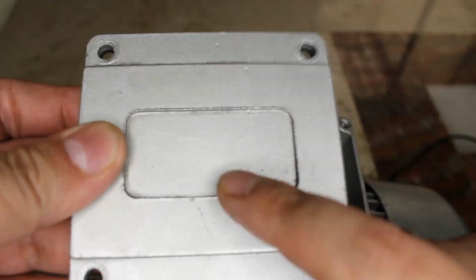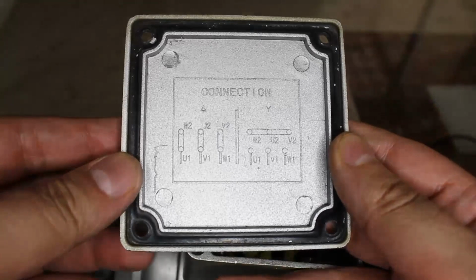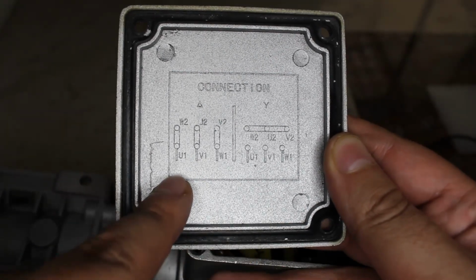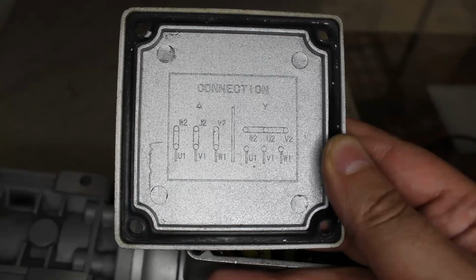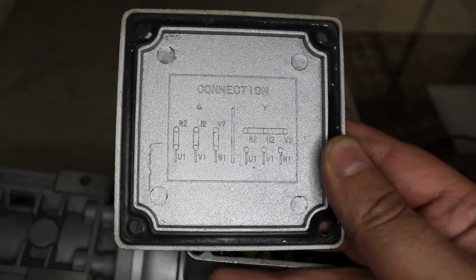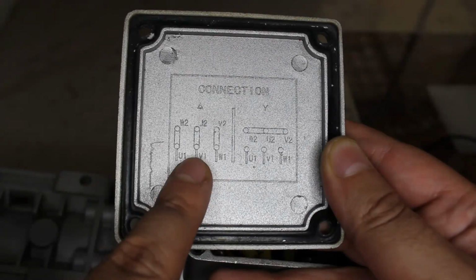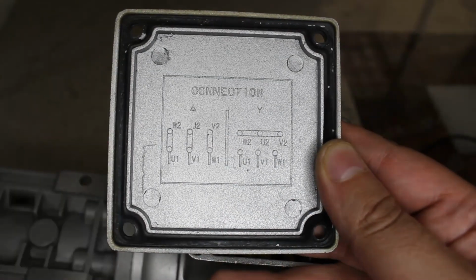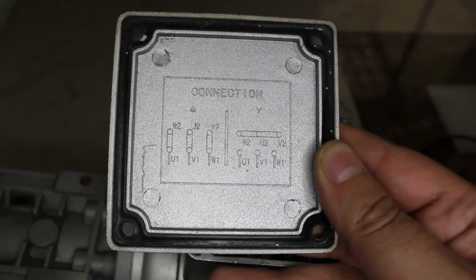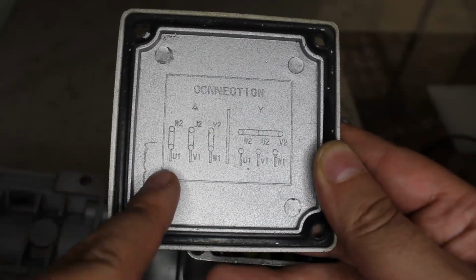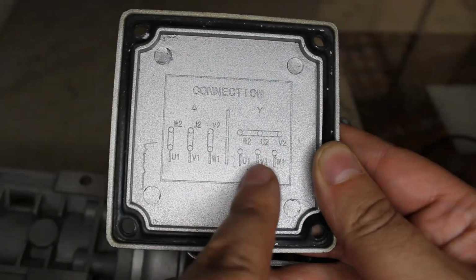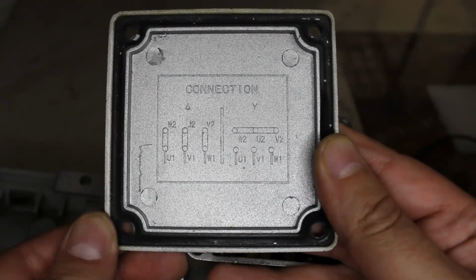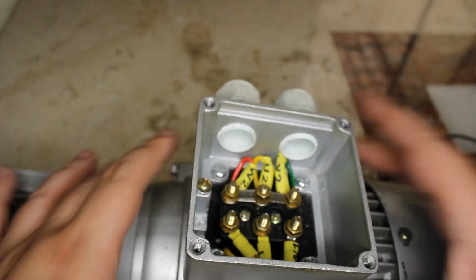Generally when we turn our plate or our lid, we have our connections, which, as I said, we need to ensure. So it says here our delta connection. What type of voltage are we talking about? It can take up to 200 volts generally. And our star connection, how much does it take? From 400 volts and up. And here it's stating how the plates should be located to get that type of voltage. Okay, so it's pretty easy.